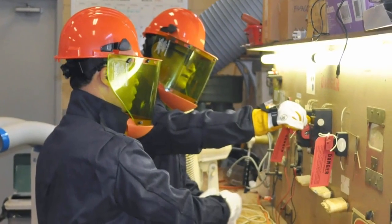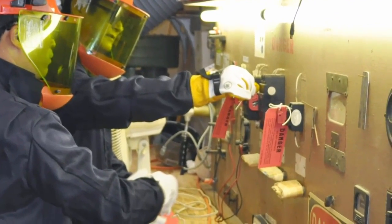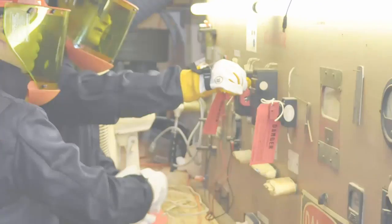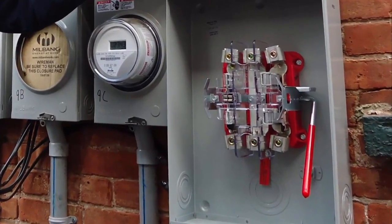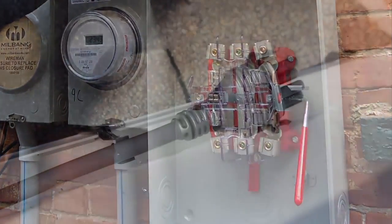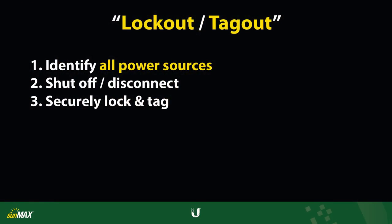Tagging means labeling equipment so that only the responsible, qualified individuals may unlock and restore power to the disabled system. Only after lockout-tagout is completely performed throughout the entire job site and the PV equipment is isolated from all power sources can you begin working on the solar energy system.